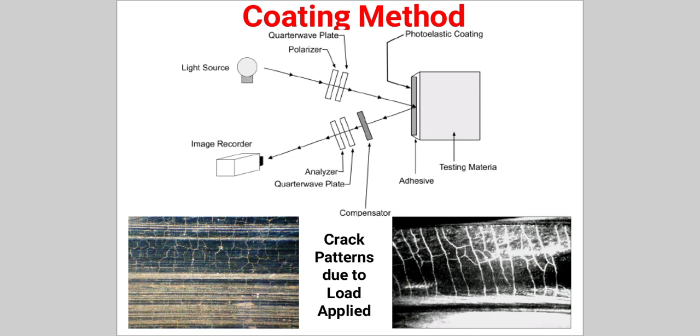But if the cracks are produced in an irregular manner, at that time we can say that the stress level is very high. Means we can say that here you will not get the quantity. By observing the quality of that particular crack pattern, we have to decide whether the stress level is low, medium or high. Therefore this method is called a qualitative method.